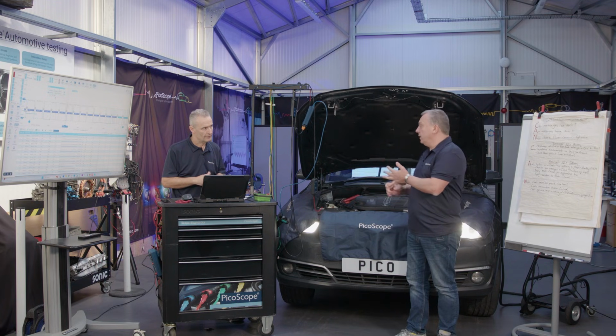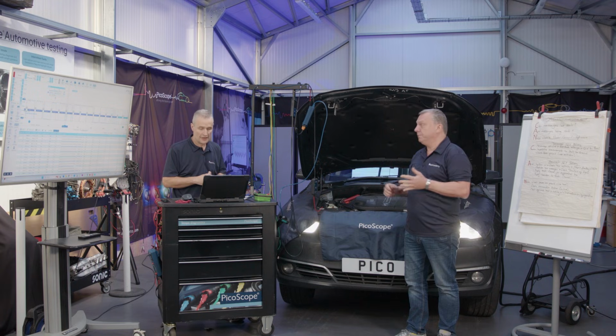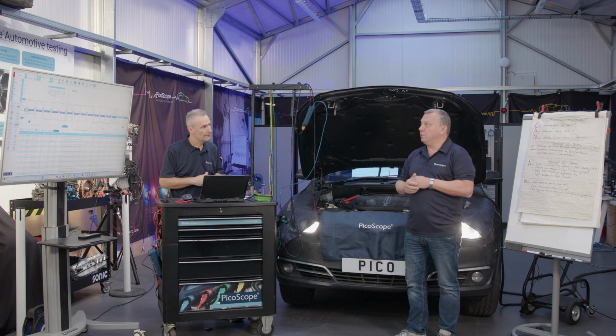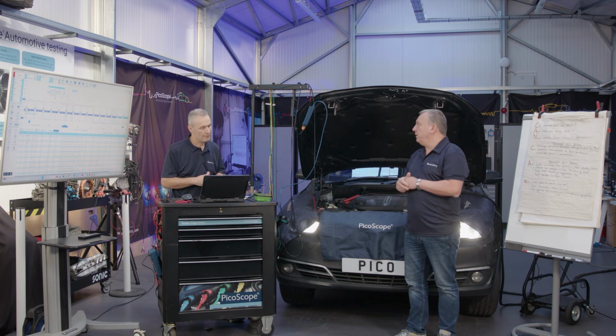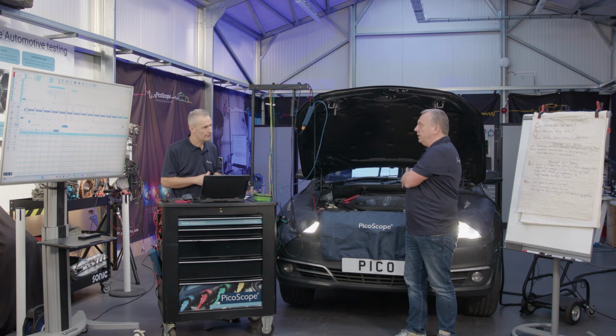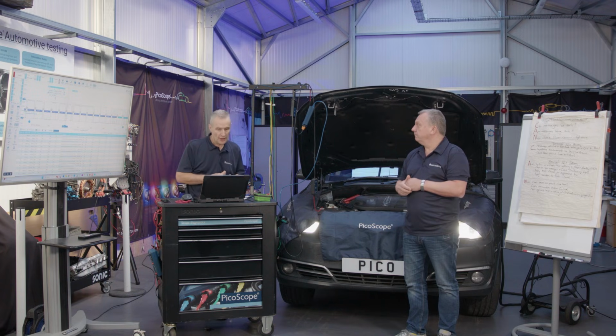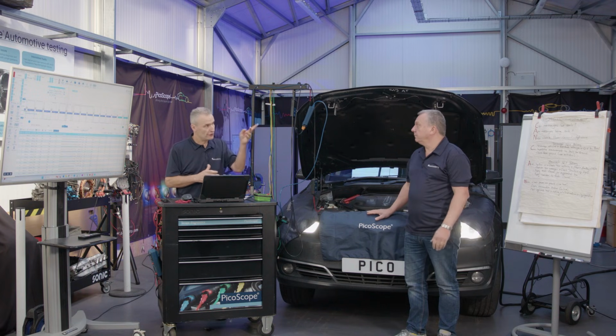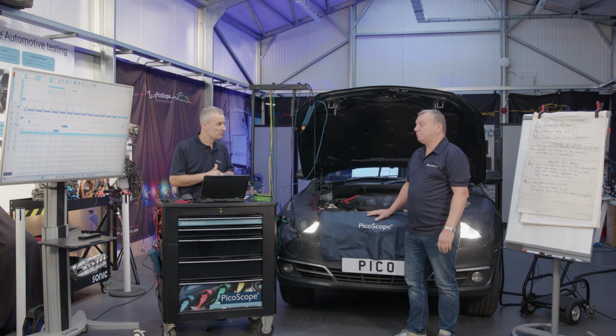Nothing wrong with measuring both channels. But you've got to make sure you're using the correct probes, because you don't want to introduce faults on the vehicle by your measuring technique. Nothing wrong either with using the differential probe to measure with reference to ground. You could, if you wanted to, use B plus to reference to ground, B minus, you could use that, but why not measure across? A winner.